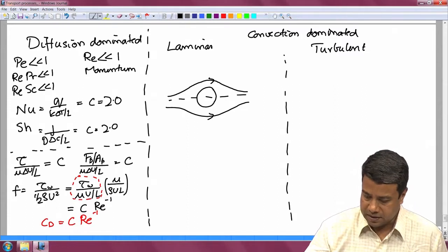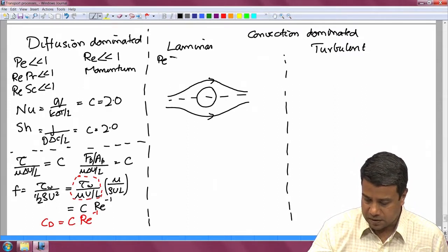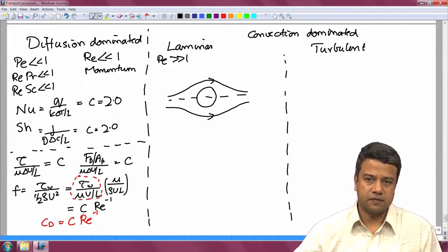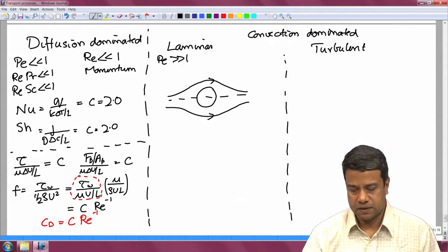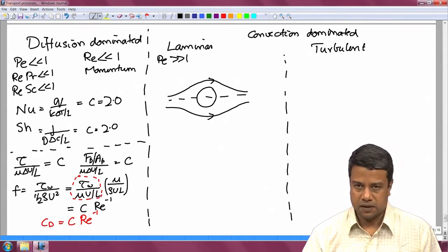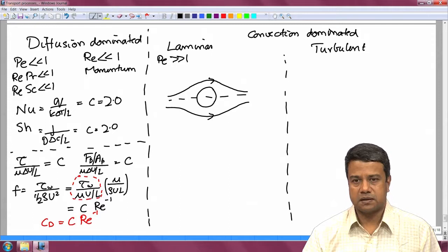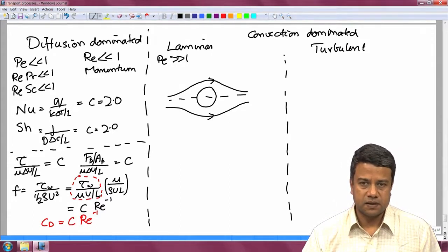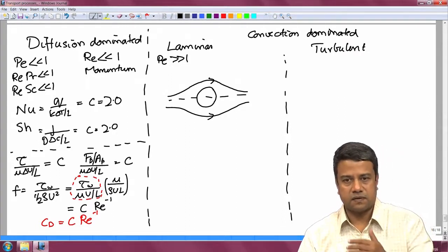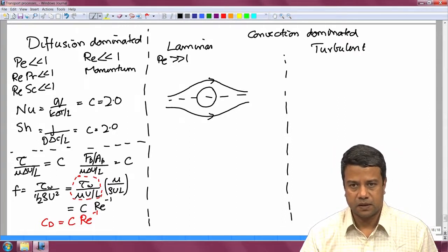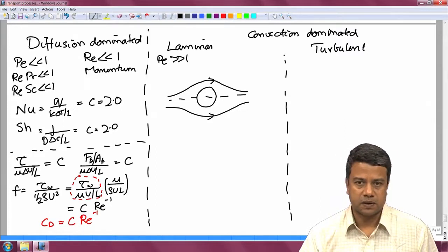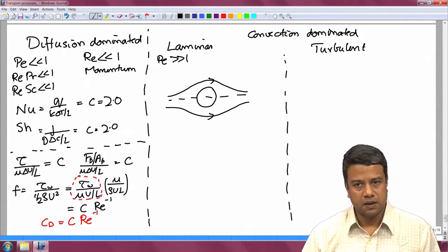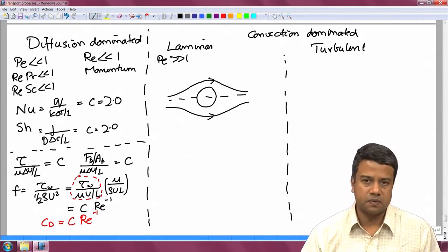That means that the Peclet number is much larger than 1. Convective effects are much faster than diffusive effects in this regime. However, as I had emphasized in the past, when convection is dominant, convection can only transport material along the direction of the fluid velocity. There is no convection perpendicular to the droplet. The convection is sweeping the moisture past the droplet. Ultimately, at the surface, diffusion has to become important.